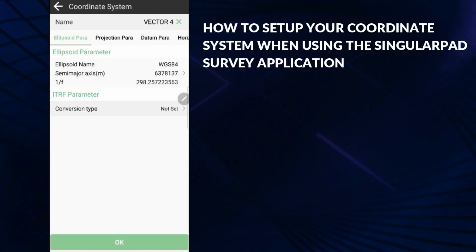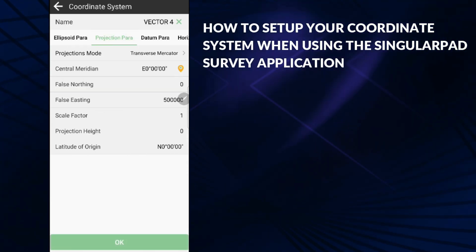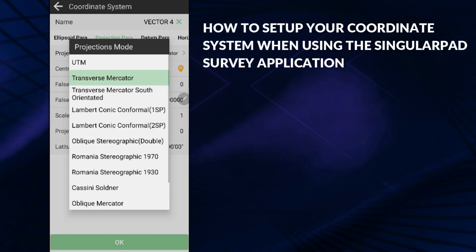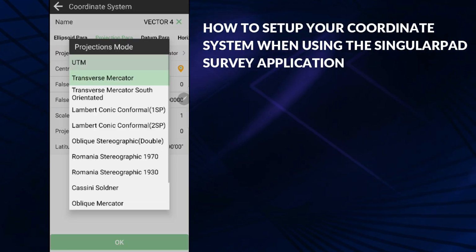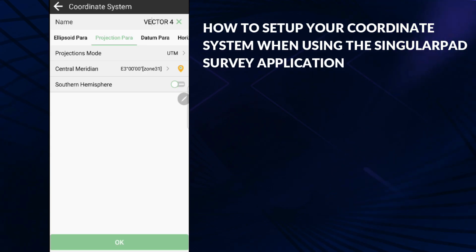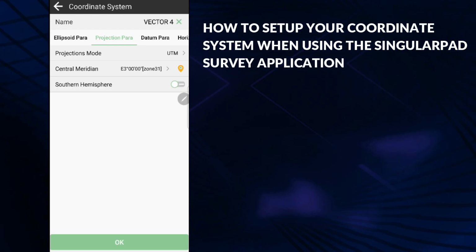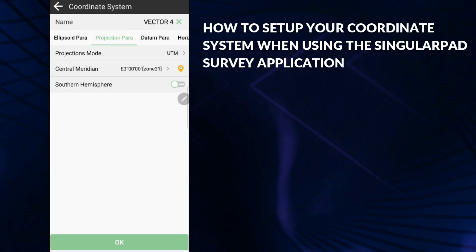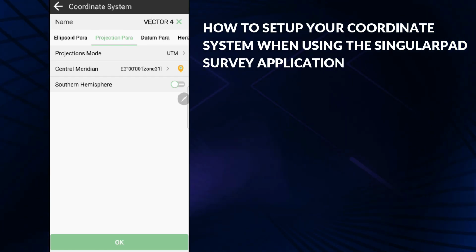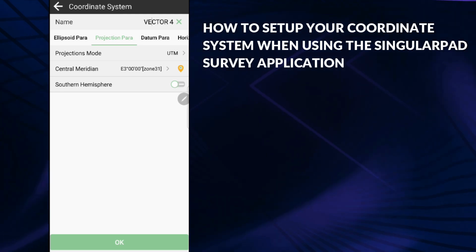So we are not going to touch anything here. So the next page, we have our projection parameters. On the projection mode, we are not using transverse Mercator, we are using UTM. So we select UTM. On the central meridian, it is going to be 3 degrees if we are using zone 31. It's going to be, I think, 9 degrees if you are using zone 32. So you select your zone. The southern hemisphere, you are going to leave it at off. So you just leave it there.